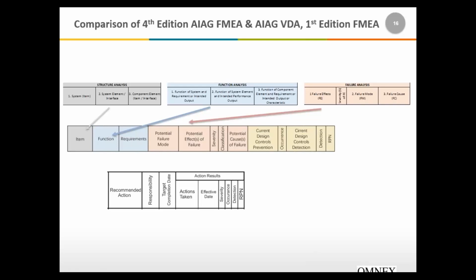You identify the failure mode of the focus element. It's actually the failure mode of the higher level element. It's the effect. And the failure mode of the lower level element is the cause. So the idea is that when the component fails, the item we're looking at fails, and it causes a failure in the system, okay? The effect is a failure.